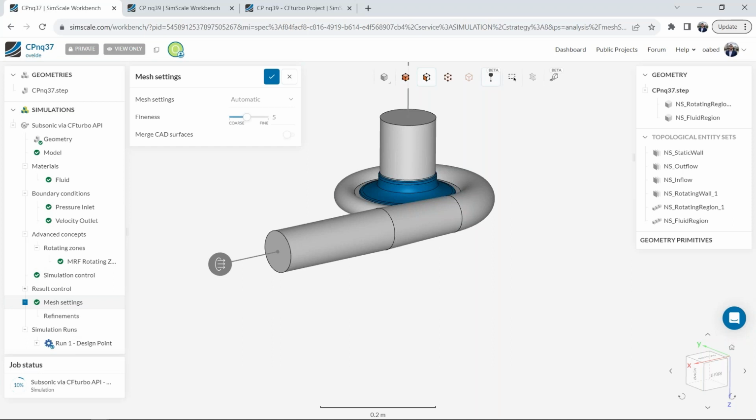In this case, it's a basic scale from 1 to 10, which allows you to step back from the mesh generating process. We're working with our subsonic simulation analysis type, which is geared for turbomachinery applications, and we're able to work with a Cartesian mesh, so we're always generating a high quality mesh even within complex geometries like a turbomachine.